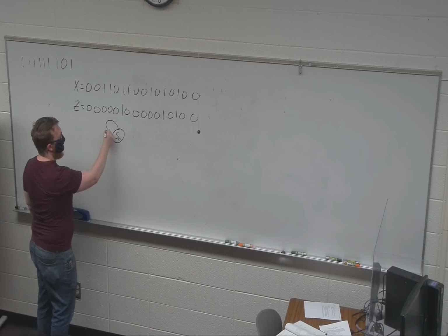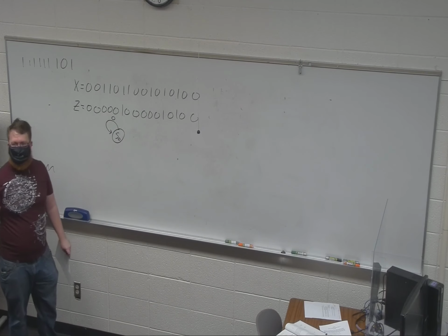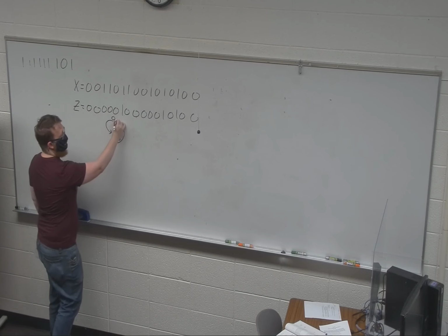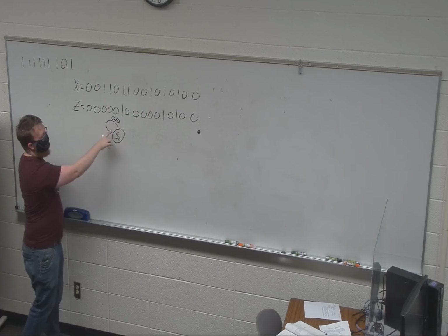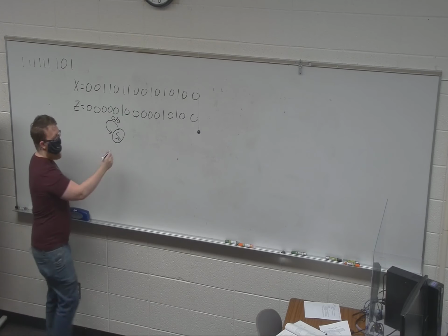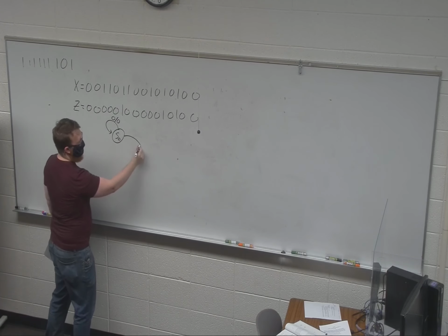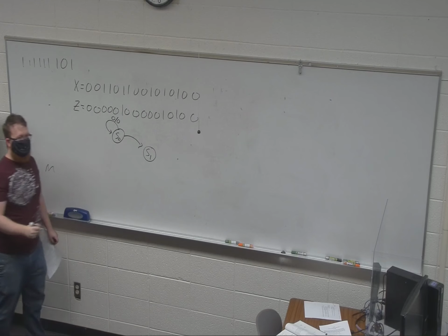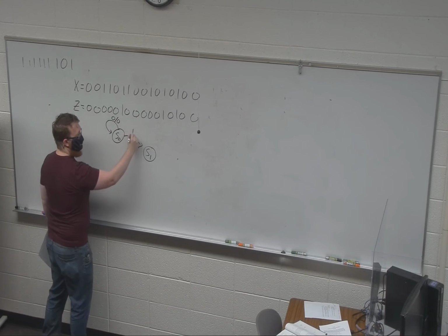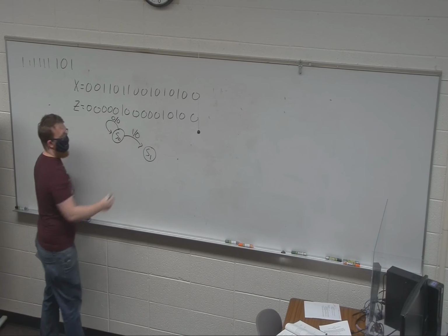Zeros are boring. And what is our output? 0. So we note it like this. We get a 0, the output is 0. So if we get a 1, we're not staying in the same spot. And we're going to give it the next state. All right? And our output is still 0 because it hasn't happened.